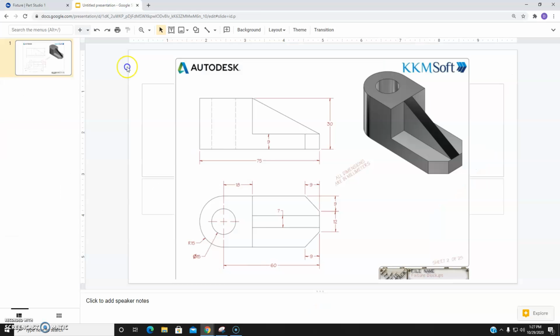So if we go back to this, I could technically have drawn this line in. However, I wouldn't be able to extrude part of this up 9 and then part of this up our total height of 30 here. I would actually need to do it as 2 separate extrusions, and therefore 2 separate sketches as well. So there's no need to add that in right away.